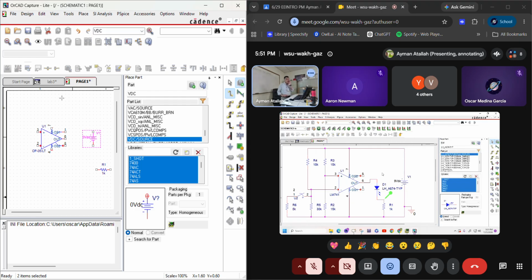So if you connect a motor here instead of this, will it run? Even if you change this battery voltage to 10 volt, will it run or not? The motor needs 1 ampere, but the maximum current we can get from the operational amplifier is like 20, 25, 30 milliampere.